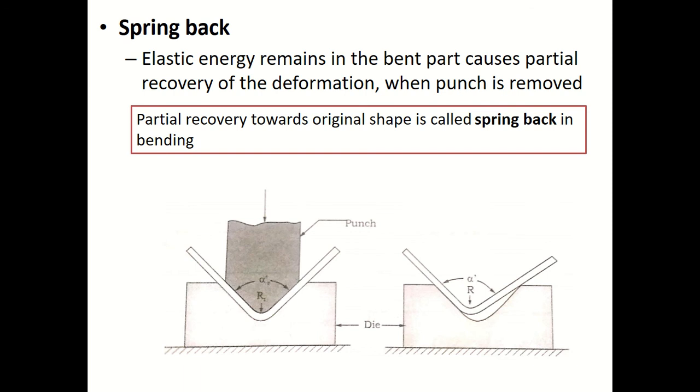Please note that the final bent angle after spring back is smaller, and the final bent radius is larger than before bending.